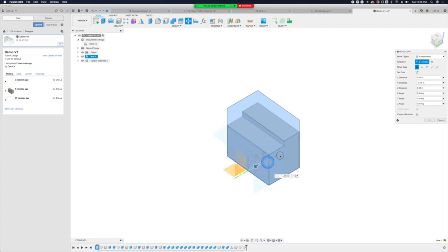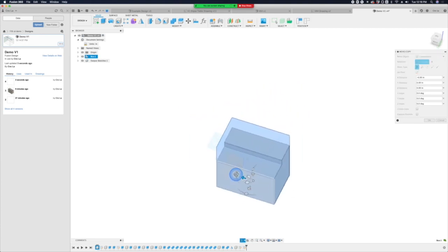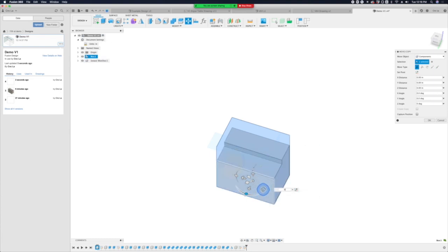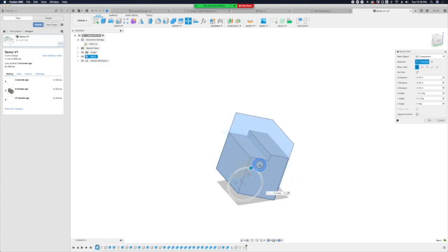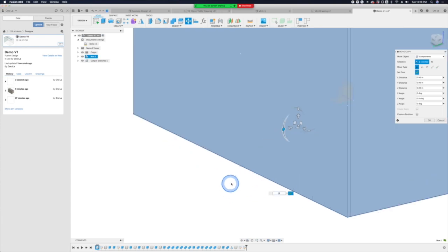These arrows are along that axis, along this axis. It's kind of self-explanatory. The handles will let you rotate. Let's say you wanted to kick this over on its edge, but you don't like how it's rotating from the middle of it, you can redefine your pivot point by picking a point anywhere on this side.